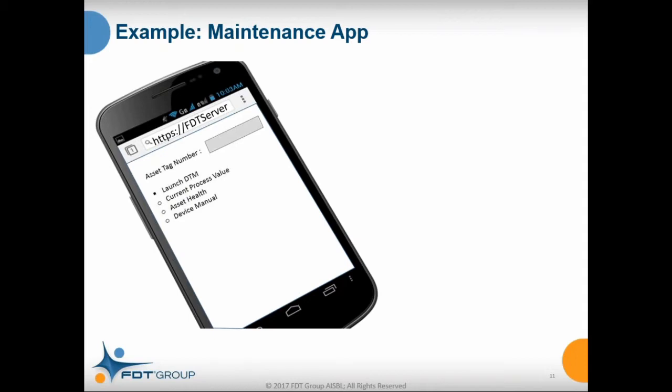But also, in terms of just a little different workflow, notice the options that this fictitious app gives. You could just launch a conventional DTM and start working with the DTM like we do today, but maybe there's some other things. Maybe there's just shortcuts. Maybe the person's just questioning, is this thing even working right now? Because it looks odd. Something doesn't look right. So show me the current process value. Just a real quick reference. Or maybe they're wondering, is there any health flags on this thing? Is there any maintenance issues popped up? Or maybe they've got to do something completely unrelated and all they're really looking for is the manual to that particular device so they can look up something.